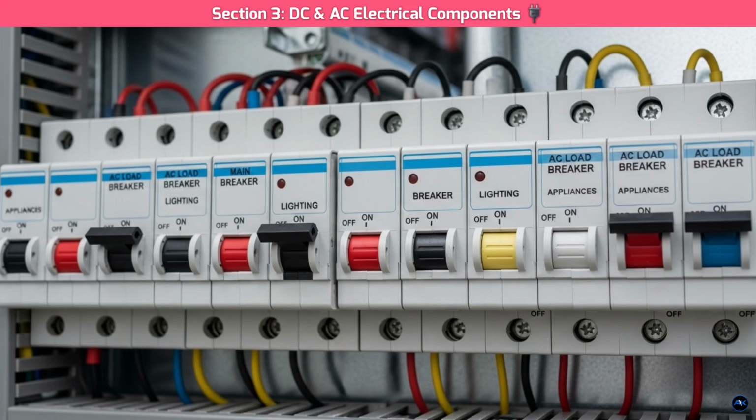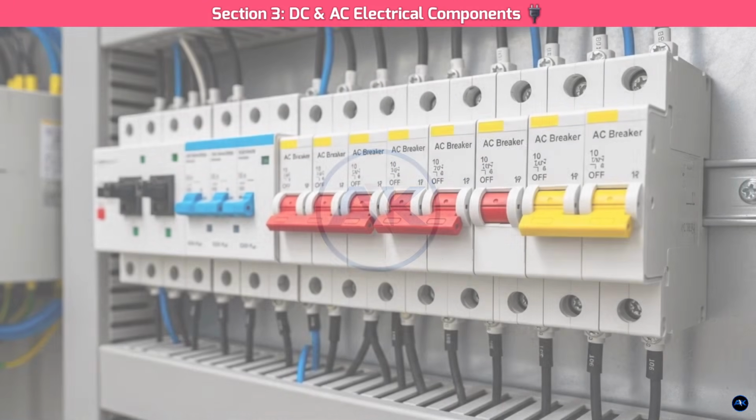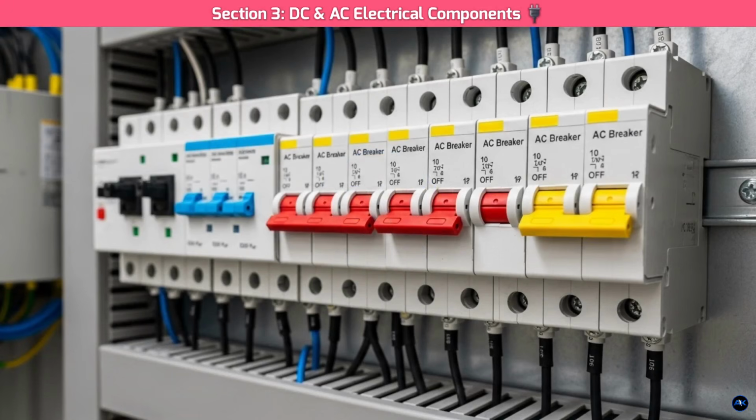When you add a solar breaker to your main panel, you must ensure that the total amperage of the solar breaker and your main breaker doesn't exceed the panel's internal busbar rating. For example, in a 200 amp panel, if you have a 100 amp main breaker and a 20 amp solar breaker, your total is 120 amps, which is well within the 200 amp limit.